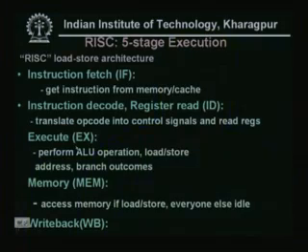Now, execute performs ALU operations, load-store addresses and branch outcomes. That means whatever instructions are supported by MIPS are executed in this execute stage. Memory means accessing memory if it is a load or store, and otherwise it is idle. Another stage is write back.